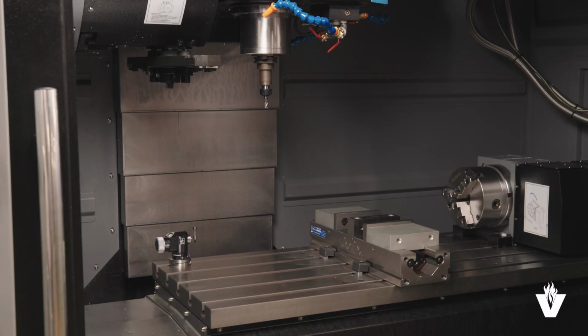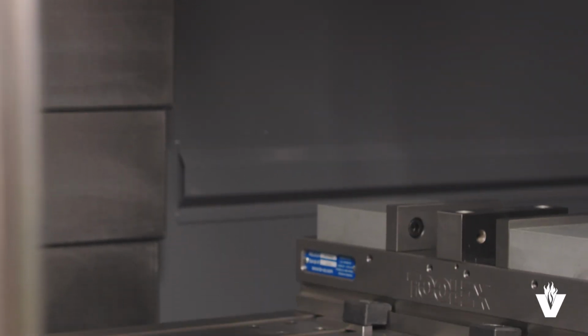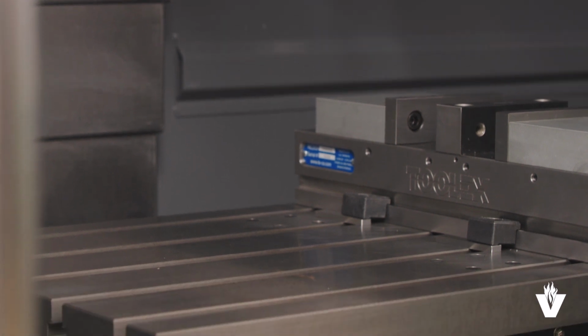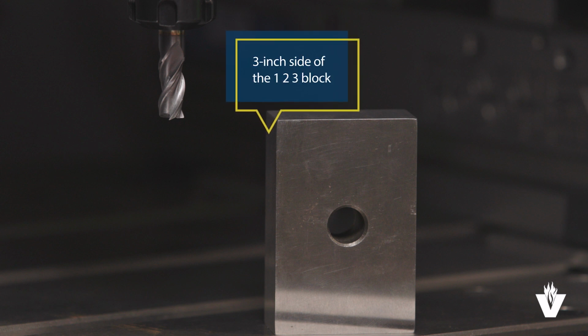Our machines are calibrated with what is known as a Z reference length. This calibrated length stored in the control is the negative distance from the spindle at its home position down to the machine table. We also have touch-off devices. We'll be using device number 3 today, which is the 3-inch side of the 1-2-3 block. With the device set, now we're ready for the 1-2-3 block and to move into position.